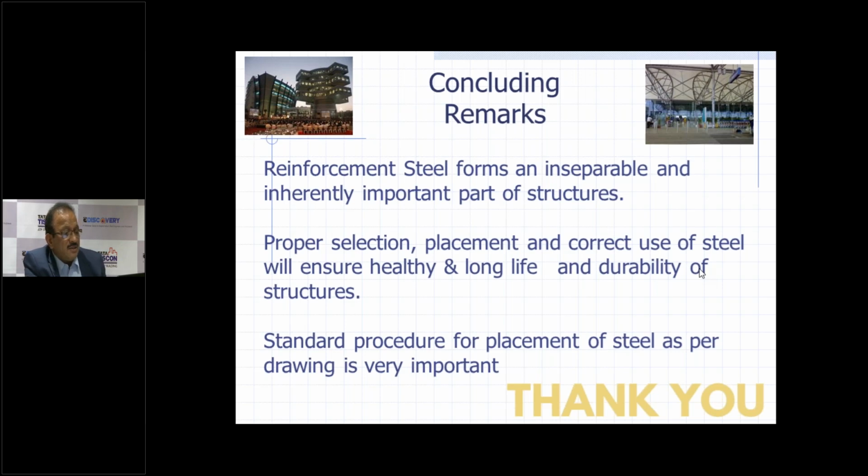Okay, then Rahul Jaiswal is asking, any suggestions for what to do with extra length rebar left after reinforcement and construction? The extra length of the bar which is left after the construction has to go as scrap. This cannot normally be used in construction because the small length of the bars will invite two laps at both ends. So not recommended. It has to go as scrap.